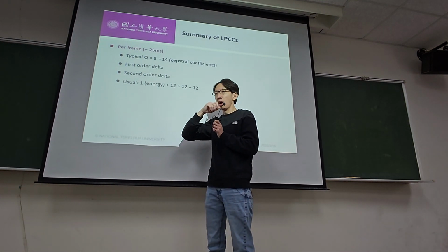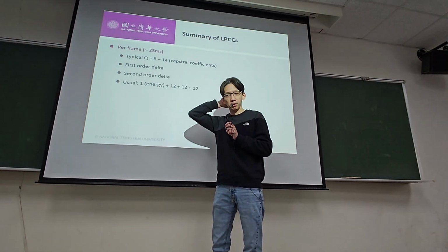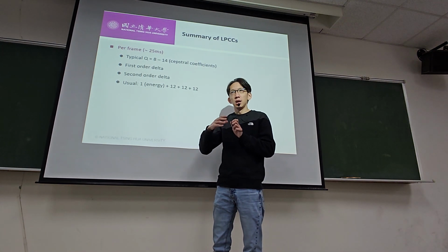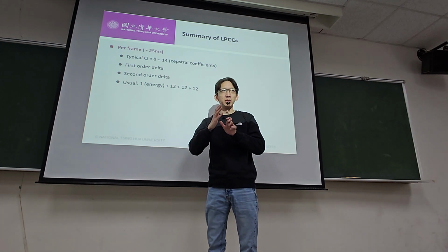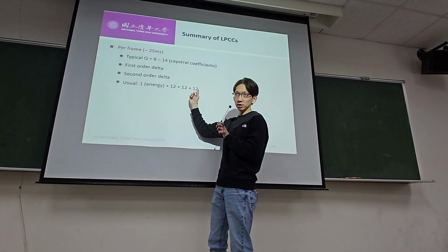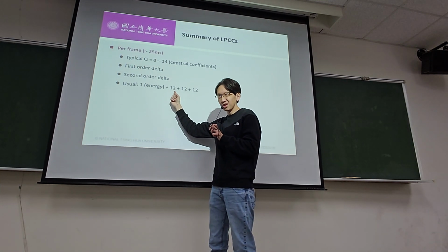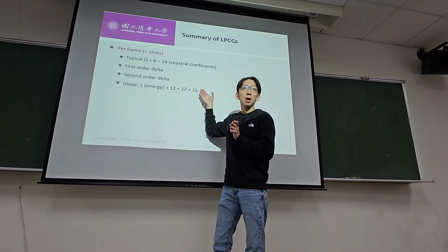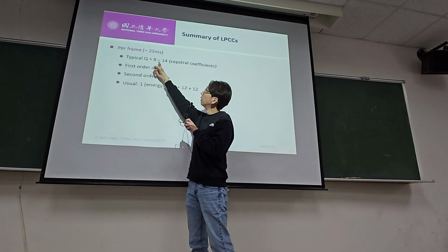One thing you'll see quickly, if you run any speech recognition toolbox and compute LPC and the deltas, is that you'll always see a number between 30 to 40 features. It's because of the delta, delta-delta, and the coefficients. People extract between 10 to 13 cepstral coefficients, then find their delta and delta-delta, and put them all together to become the feature vector per frame.